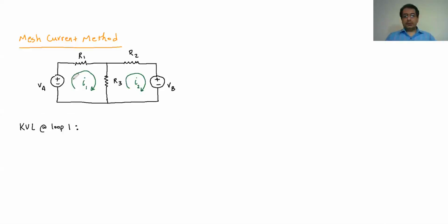What the Kirchhoff voltage law says is that if I add all the voltage in that loop together, it should come as 0. In other words, sigma V in the loop should be 0. So if I start from this point here, for example, and go around and come back, I write the Kirchhoff voltage law.